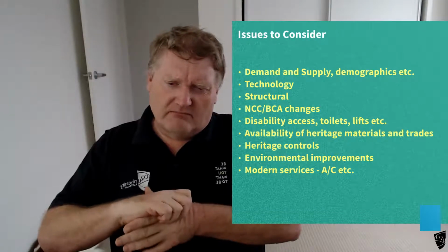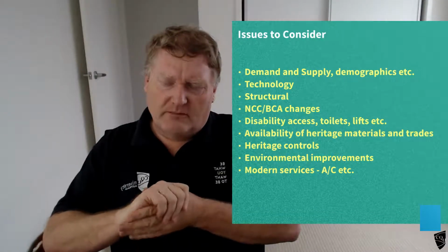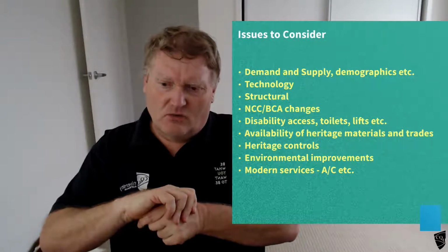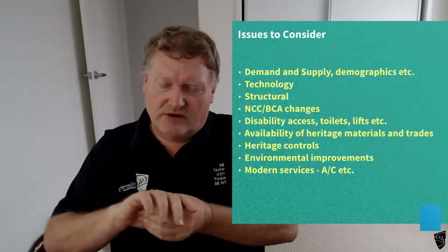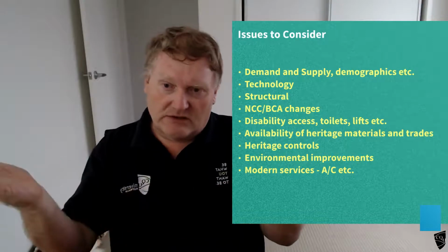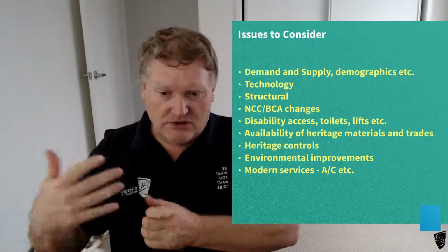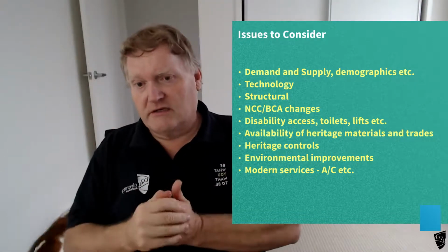Insulating walls and that, because they're normally solid load-bearing walls, can be difficult. You won't be able to cover them on the outside in most situations. Like the bank's got a stone frontage, you can't cover that with insulation. You'll probably have to insulate internally.